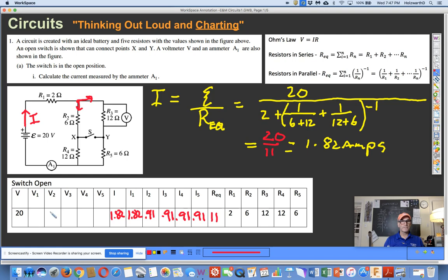So let's fill in these voltages because we might be able to refer back to them and answer questions quickly. I know that part 2 of A wants to know the voltage drop across R3. So in doing so, finishing up the chart, that's what we get. So be a little patient here at first because I might have to pull out my calculator. All right. So the voltage drop across R3. If you know I3 and R3, you can find V3. So that'll be the voltage across R3.